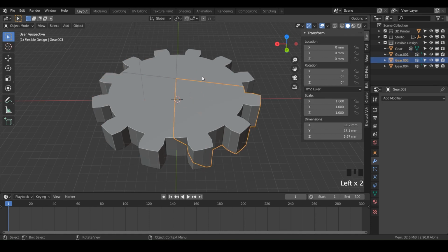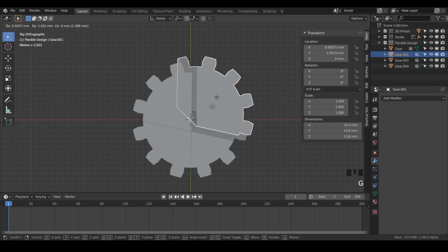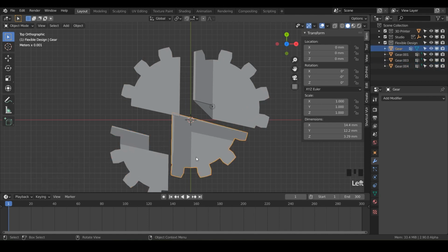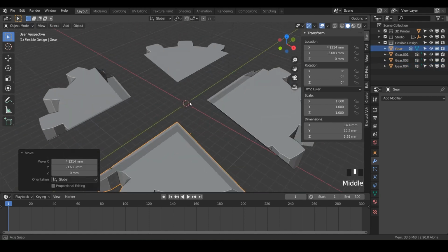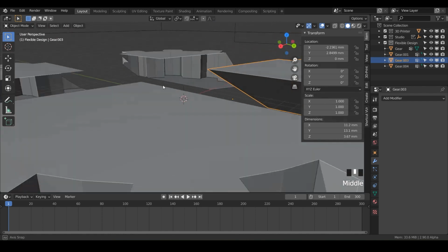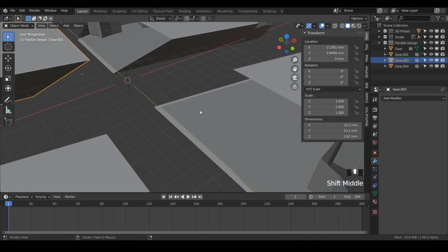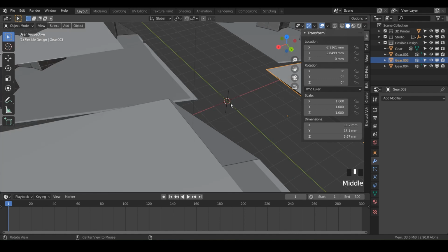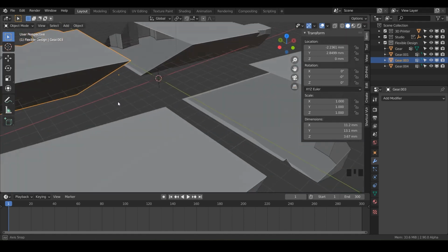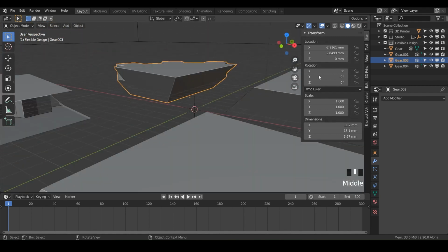And so now we need to get these ready for 3D printing. So I'm just going to go to top view and kind of just space them out. Just grab and space them out just a little bit, just so we can kind of see what we're working with here. And so notice we've got some weird stuff going on here. We've got one that's completely watertight. We've got one here with the big opening, and we've got 2 that have big holes in them. And so I'm going to show you how to fix all of these really easily so that you can make these all manifold.